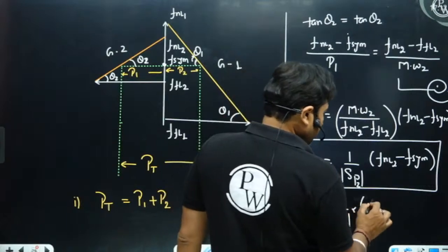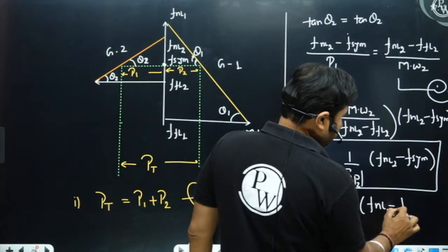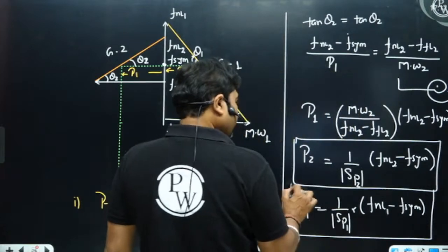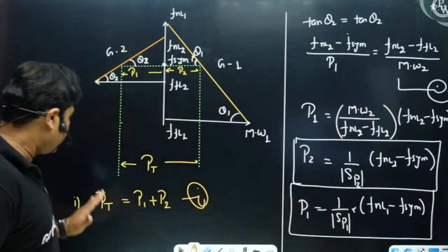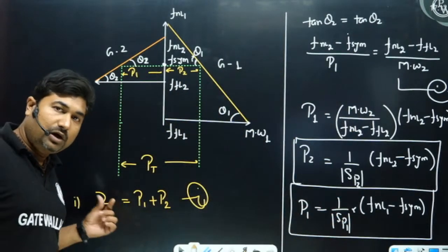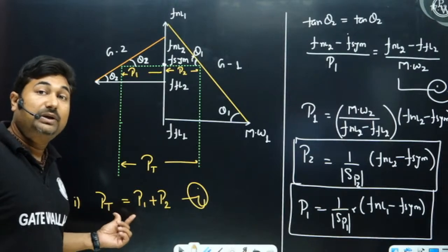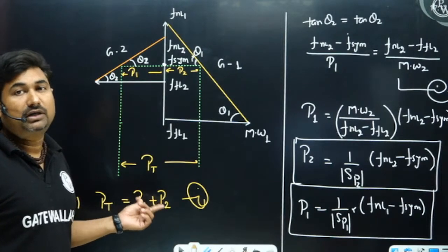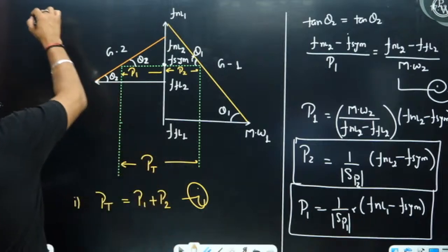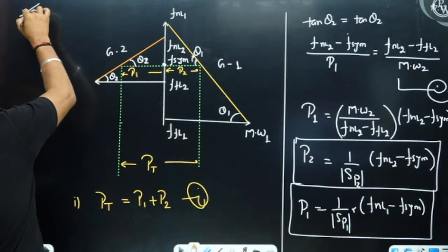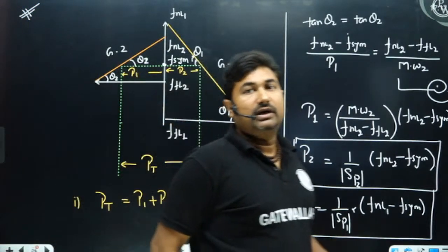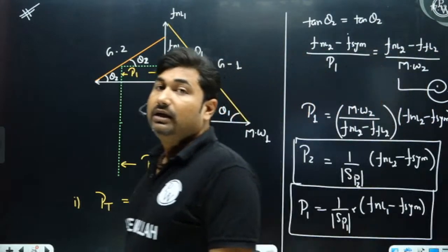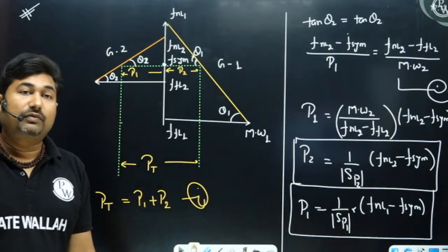So P1 is FNL1 minus F of the system over the slope. Now we have P1 and P2, so you can put them in the equation in order to calculate the system operating frequency or the load shared by each alternator during parallel operation. This is very helpful when n number of alternators are connected in parallel to feed a load. Hoping all of you are able to understand.